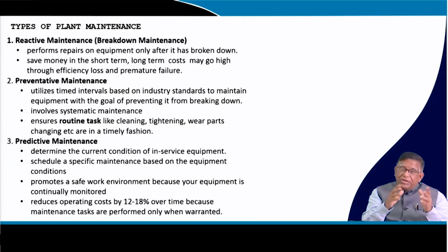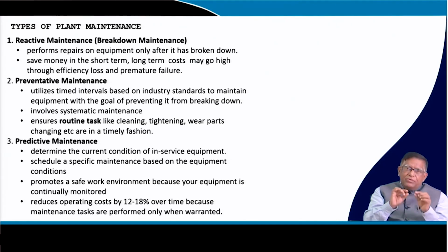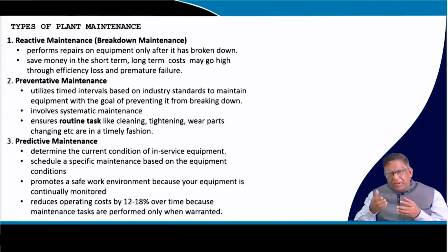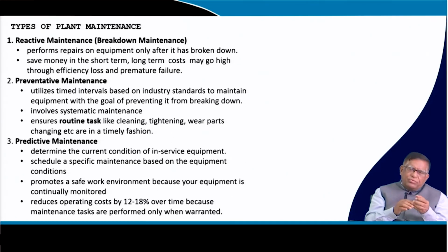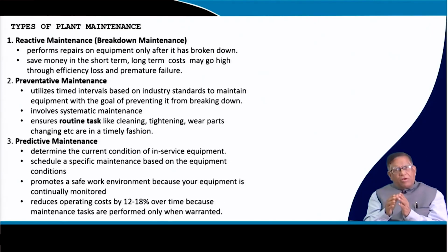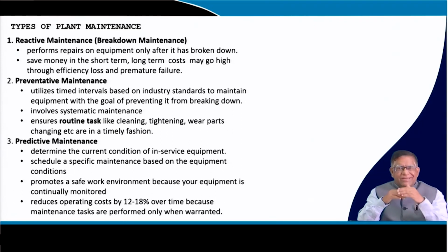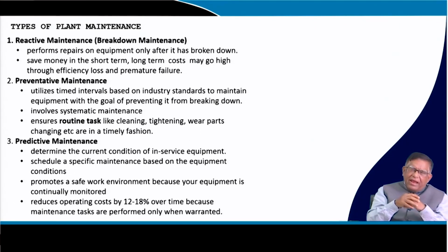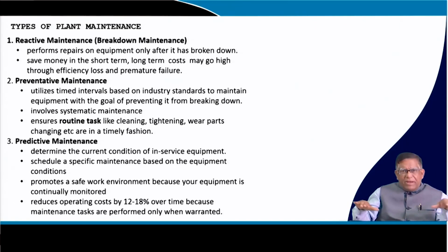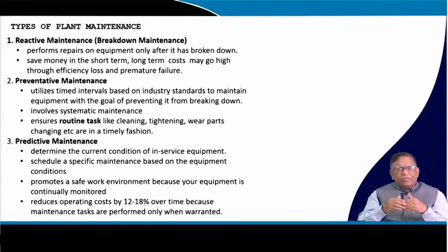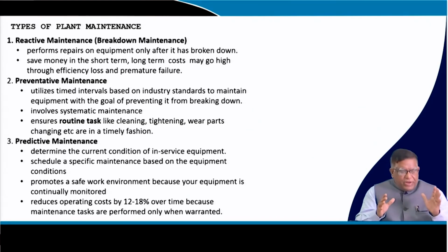All those things are monitored, and then you stop for doing the cleaning. If material is going to the return belt over the crown pulley, or any material is getting trapped between the conveyor and the end pulley, you remove it. Below the conveyor, if materials have piled up, remove it and clean it, so that operations can go on. So that's preventive maintenance.